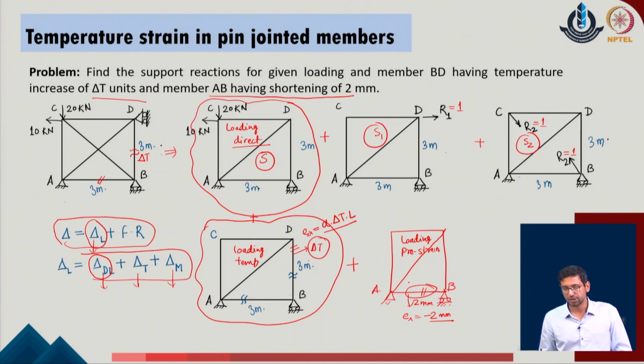Now, with respect to these two criteria, we understand that in the given problem, when I am trying to calculate the redundant values and their corresponding displacements, for the calculation of delta 1 due to the direct load in the given system, I would have evaluated the given system as an integral, or as for the truss, we can directly do the summation. So, we define it as the summation over members 1 to m of S1 S L upon AE for the given system.